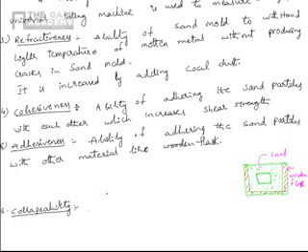After completion of the manufacturing process, you need to break the mold, right? If the mold has more cohesive and adhesive strength, it will stick to the mold box, and you need a huge amount of external force to break it. To avoid that, the collapsibility property has to be there: the ability of breaking the sand mold with a little amount of force.